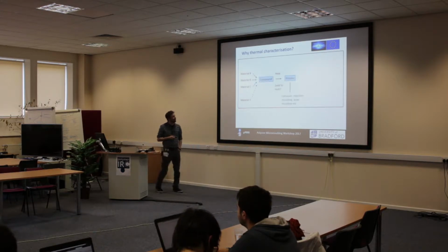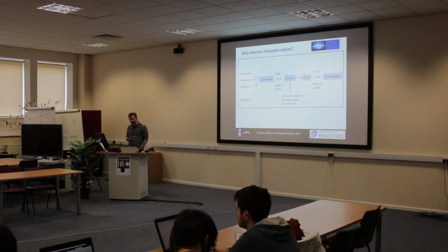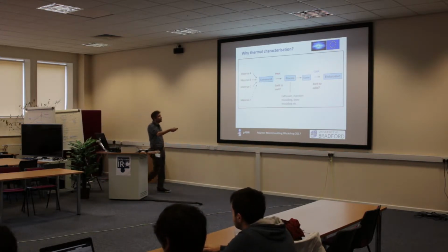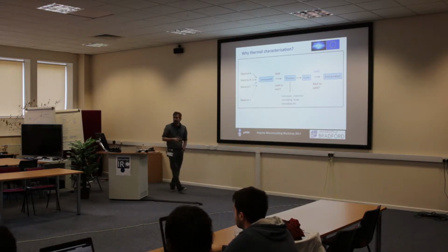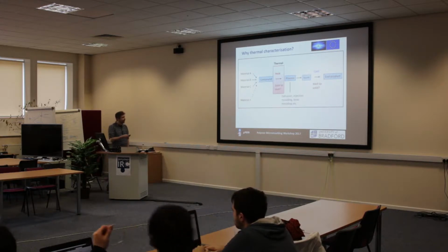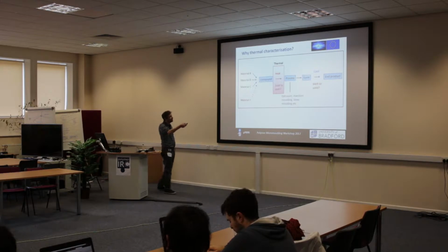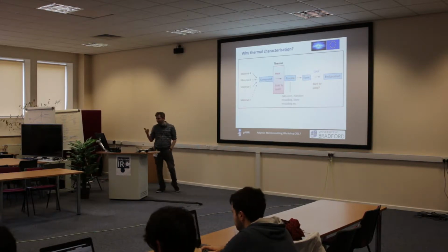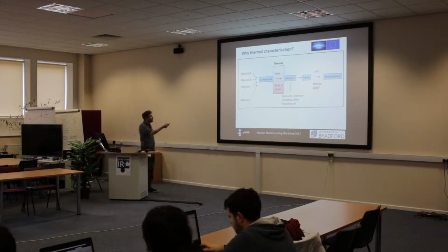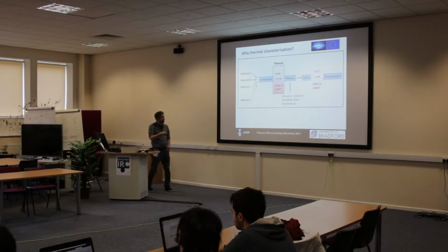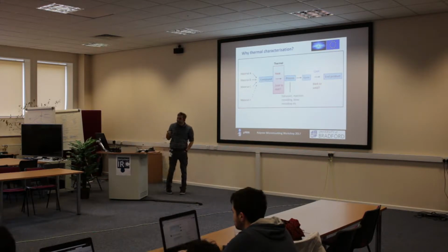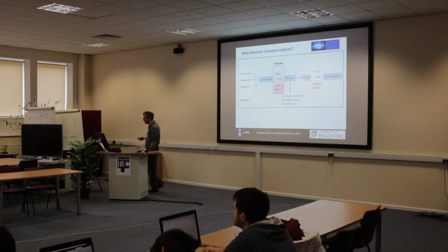Okay, so just looking at this image again, we're looking at a different side of this than we were yesterday when I was talking about rheology, where we focused pretty much on the flow section of the manufacturing process. Today we're going to look a little bit at this thermal section here. So we're basically going to take our material in pellet form or powder form, whatever it happens to be. We're going to compound it, mix it with whatever we need to mix it with, and then we're going to heat it up, and go from a solid to a melt, or at least something that will flow.